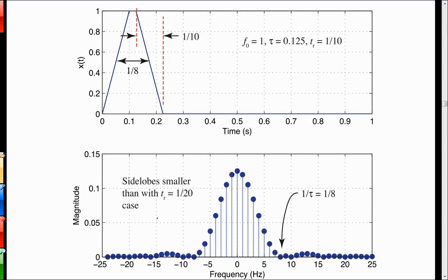It's a curiosity thing, but it lets you know that if you slow the edges down, you slow down the harmonic generation, and that can be an advantage if you're trying to limit the amount of high frequency radiation from something too.